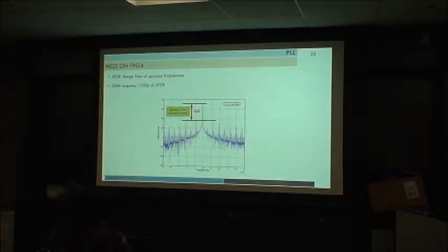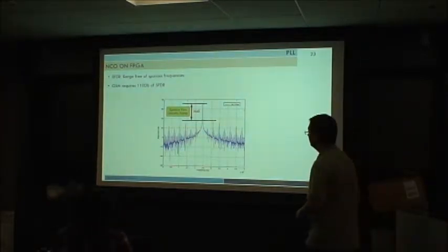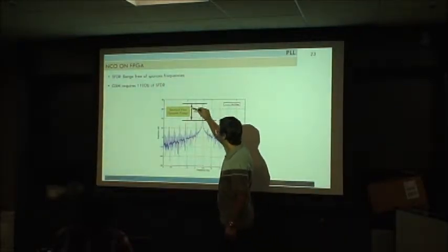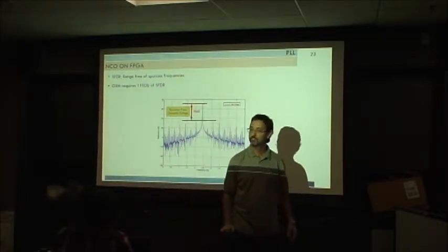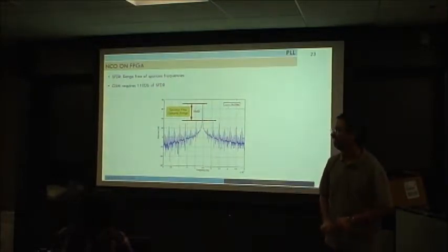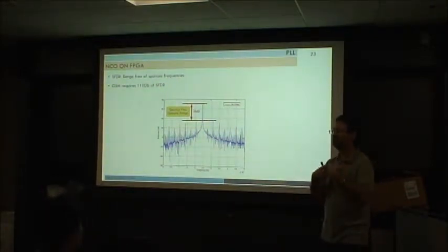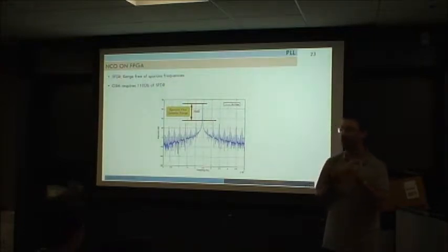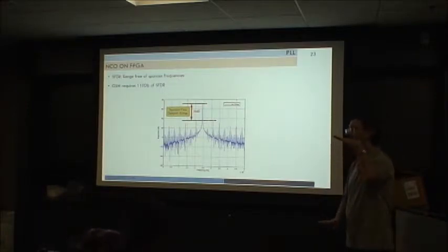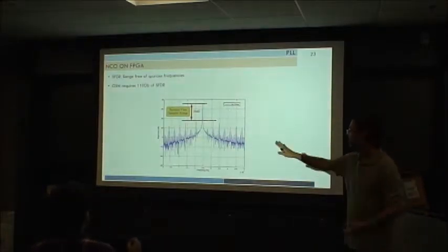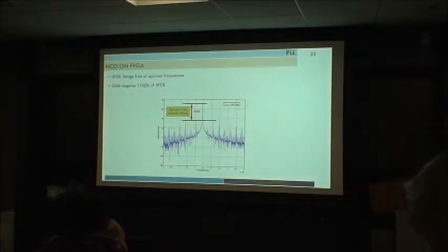This is just to give you an idea from the first example. If you measure, this is the spurious-free dynamic range that you have, 56. Just to give you an idea, GSM needs 110 dB spurious-free. So if you want to receive a GSM signal, your LO should be really pure, 110 dB of spurious-free signal. So you cannot recover GSM with this, and of course, forget about LTE.